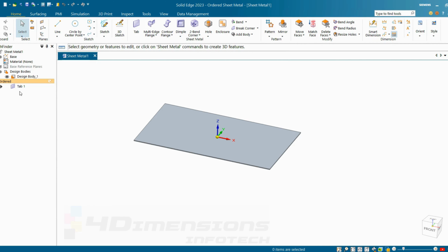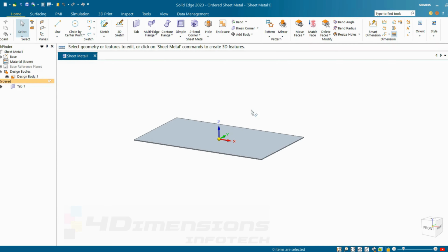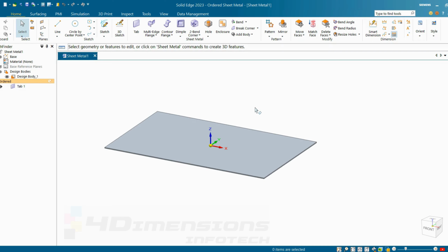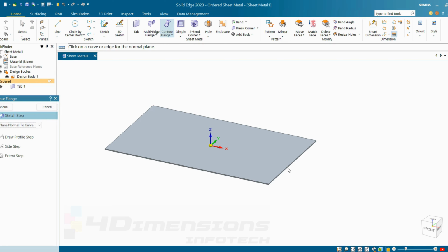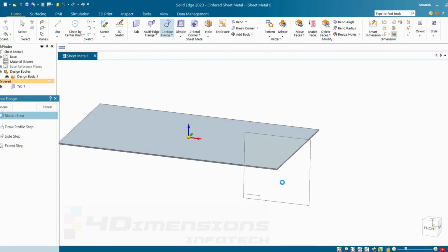We have deleted the earlier flanges and now we are going to see contour flange by taking the direction of the horizontal flange on the inner sides. So for that I am going to make the sketch here. I will select the command first, then select the reference edge. We'll go for the plane here. At whatever end we want, I'll take it on the front side.